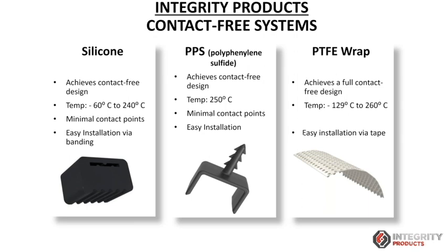For the installation of this type of spacer, we need a banding. It has to be placed on the pipe in a circumferential way, and with the banding, we just keep it tied to the pipe surface. The benefit of this system is that it's good for systems having vibration, because with vibration there could be some slipping of the spacers, or they can get misaligned, or they can get damaged. So it's meant for systems with vibration.